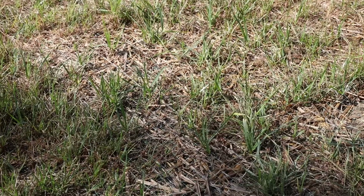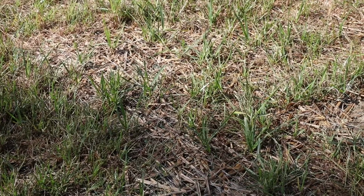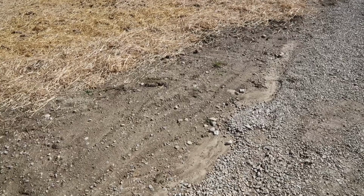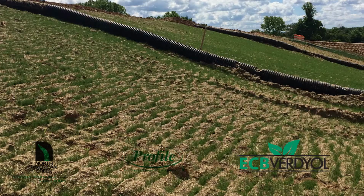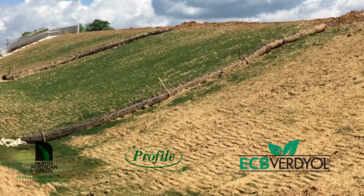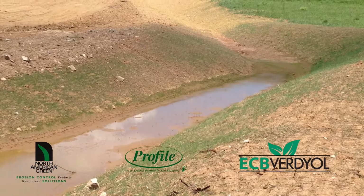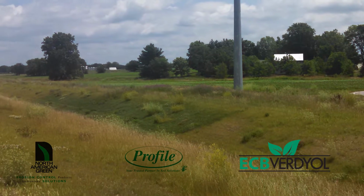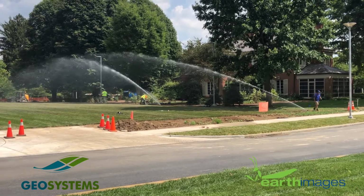Use anchored mulch to protect the seed bed, to retain moisture, and to encourage plant growth. How to maintain. Repair damaged, bare, gullied, or sparsely vegetated areas and then fertilize, reseed, and apply an anchor mulch. If vegetation fails to grow, consider soil testing to determine soil pH or nutrient deficiency problems. Other seed or seed mixtures may need to be selected. If using sod, keep moist until fully rooted.